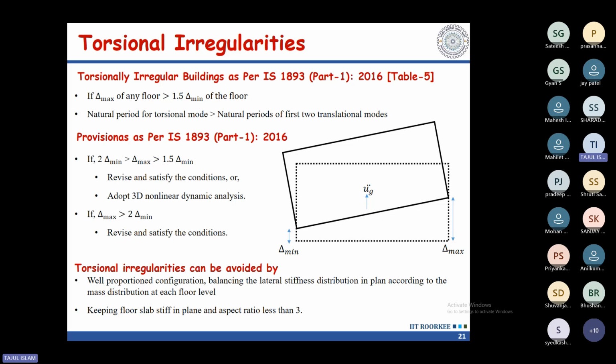And the another thing you have asked, why linear time history analysis is not sufficient. When you are performing linear analysis, you are only getting the forces. You are not getting the capacity.